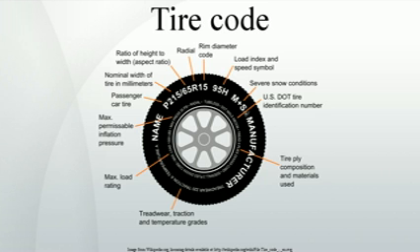ETRTO produces a standards manual, current edition 2010, which contains a number of specifications and tables. The load index table, 2010 page G7, lists the load index from 0 to 45 kilograms, 0 to 99 pounds, to 279 to 136,000 kilograms, 615 to 299,829 pounds.